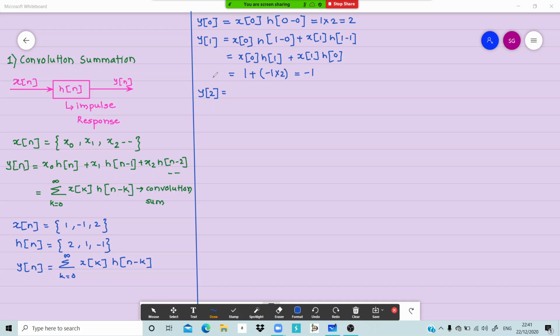But as soon as you take the Z transform, this convolution gets converted into X(z) H(z), right? And the work becomes very simple, and that's one of the advantages of the Z transform. If you can remember, one of the properties I told you, convolution summation gets converted into simple multiplication.